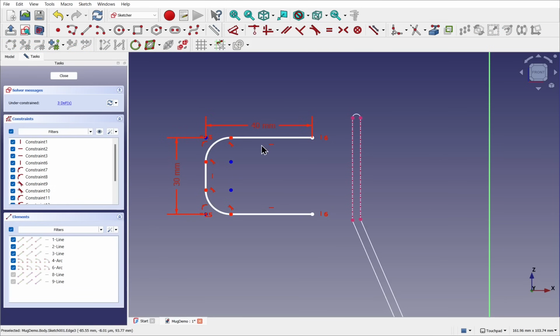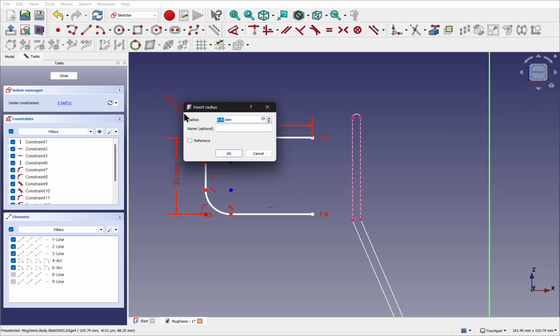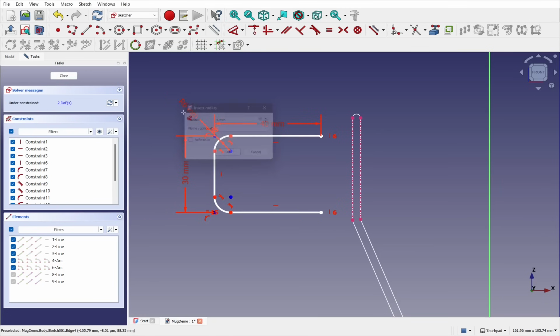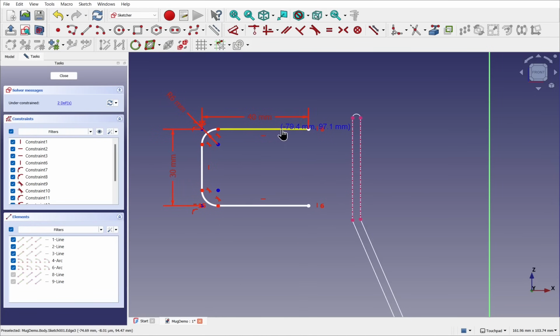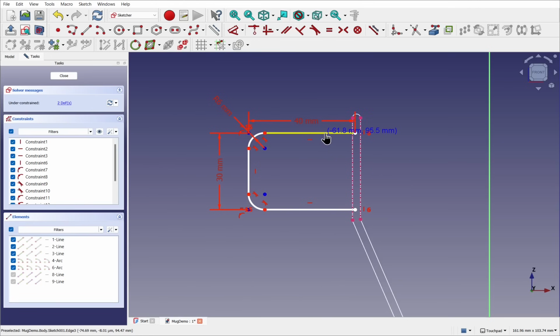an equality constraint. I'm going to take this fillet, and we'll set some radius. Let's use the dimensioning tool again, and we can set the radius here. We'll set it to 6 millimeters and hit enter. Right click or hit escape on the keyboard to cancel the tool. This is now movable. And as we said, we want to set this into here.